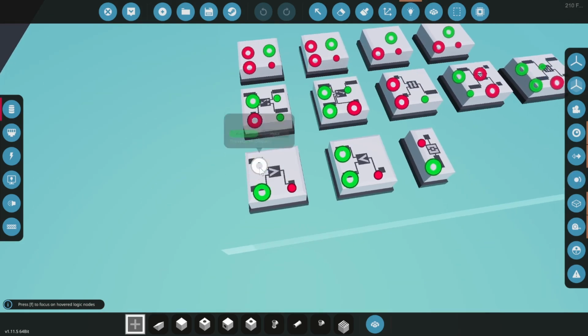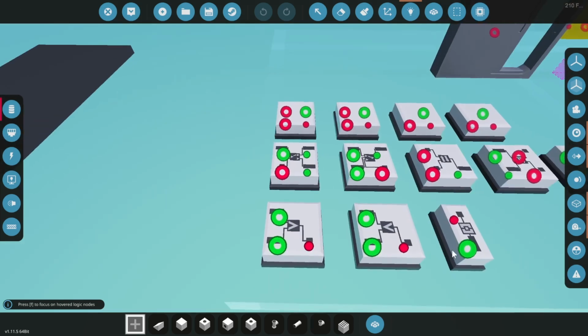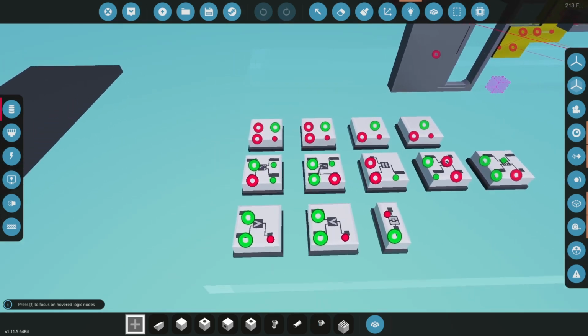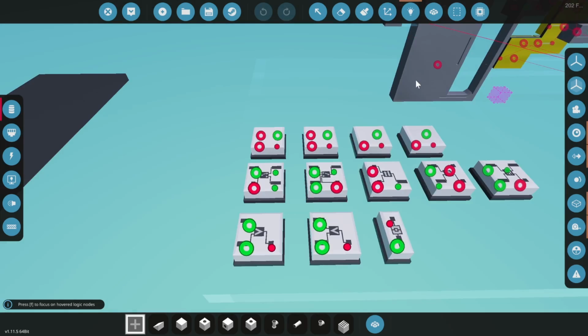But so yeah, you can see here, this is the value to compare. So this is the value that you're taking in, and this is the value you want to compare it to, B. And then it outputs a signal: outputs an on signal if A is greater than B, outputs an off signal if A is less than or equal to B. So pretty straightforward. It tells you, I love the descriptors. Now let's get this actually installed onto the demonstrator.